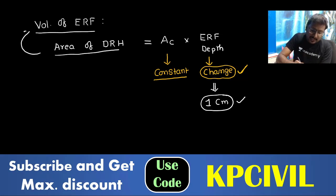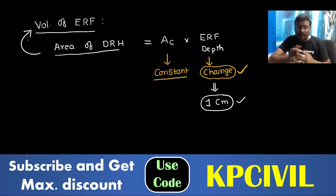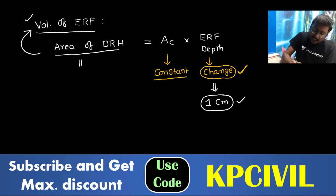So when area is constant, volume of ERF is constant. So for every rainfall, area of catchment is constant. Then Sherman made effective rainfall depth constant at 1 centimeter, so that area of DRH, which represents volume of effective rainfall, is also considered to be constant. So area of DRH, depending upon the shape, you may take as discharge into time. This is also said to be constant.